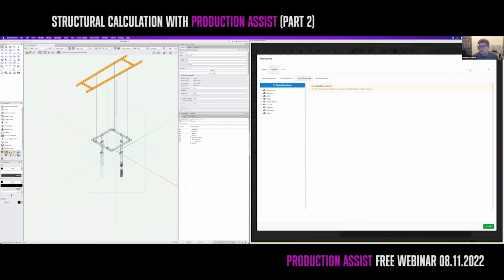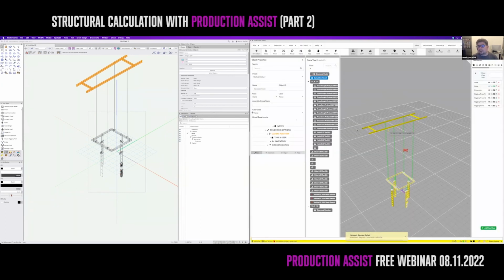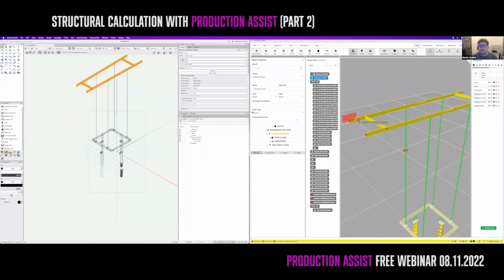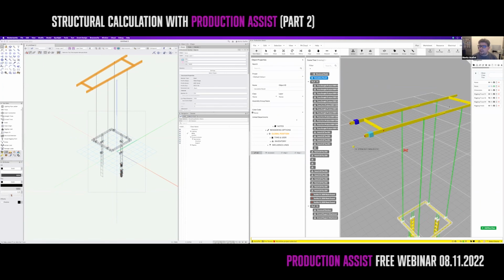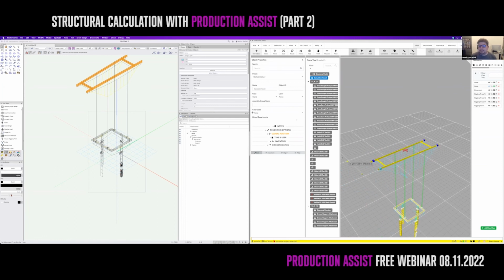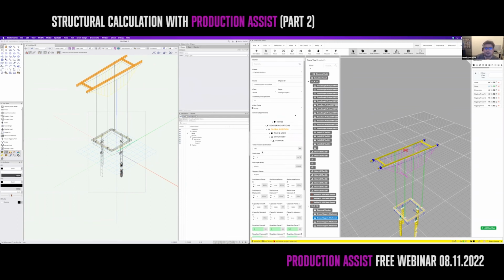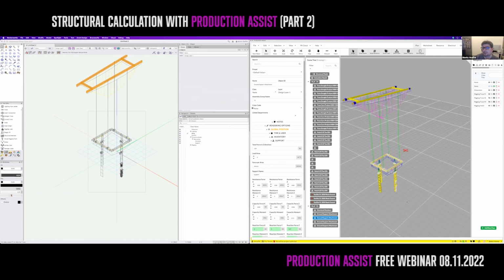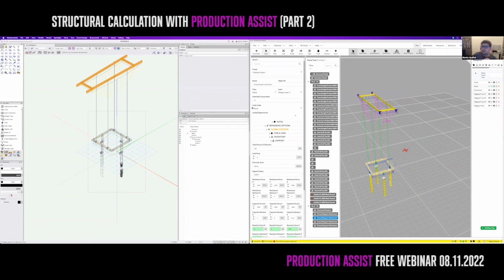Now use the new object tool and search for supports for the roof structure. Search for ground support attachment, select the ground supports, and attach this to the actual roof structure in order to define the local supports of this. You see now it's actually calculating it with the supports on the roof structure. When clicking on one of the supports, you can easily look at how much load is actually put onto the roof in here. So you see it's really easy in Vectorworks to draw complex structures and even include the actual roof into it.